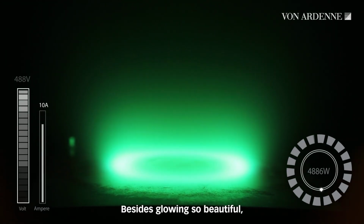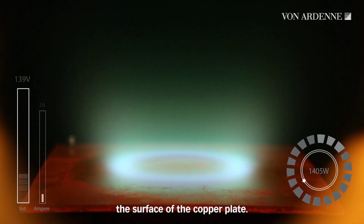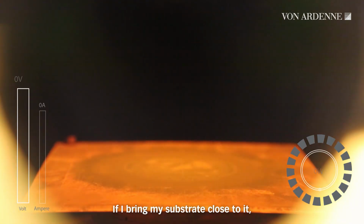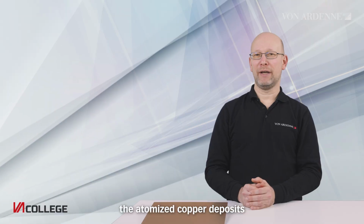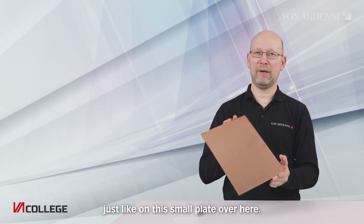Besides glowing so beautifully, the plasma atomizes the surface of the copper plate. If I bring my substrate close to it, the atomized copper deposits as a thin layer on the substrate, just like on this small plate over here. This whole process is called sputtering. Let's take a closer look at what's happening there.